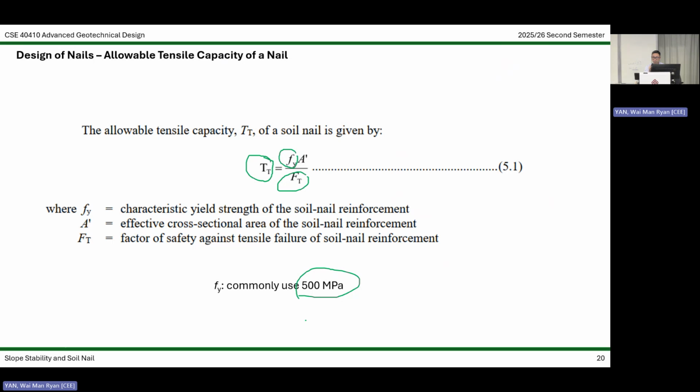Okay. Think about that. Normally, when we work with soil or geotechnical engineering, we always talk in the order of kPa, strength, right? C dash kPa. We seldom touch MPa. Why? MPa is very large. And that gives you some sort of idea that this mechanism should not be controlling. Steel is so strong, should not be controlling. We still need to check, but unlikely this is controlling.